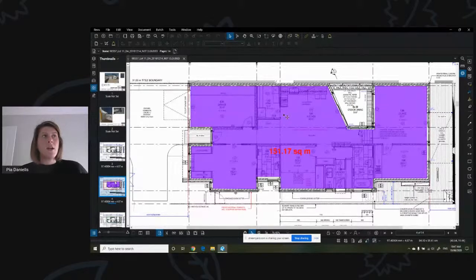We're looking at the amount of heat flow in and out of the building that is affecting the internal air spaces. So that's why it's taken to the inside of the external walls. You don't have to worry about the internal walls, like the area that's taken up by that, because we're only after an estimate, which is just a prediction. So we want the process to be quick and simple and not take up too much time. And we're also including the garage in this measurement. So you're taking in the garage floor area as well.